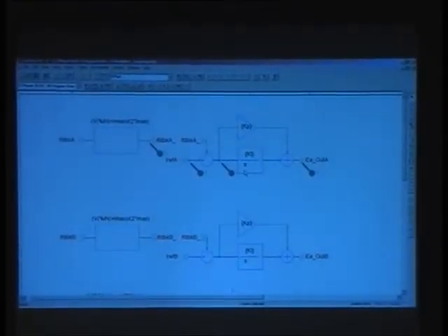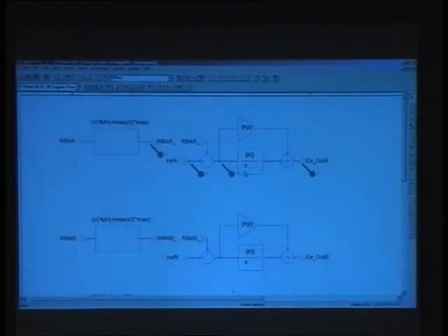You have I reference, you have I feedback, and then you have a simple PI loop. Here also we can run a Bode plot because this is a pretty linear system. So we can do a Bode plot and we can also do compensation. You are saying there is non-linearity of the torque, no? That's good. We can still do a Bode plot with non-linearity as long as there's no discontinuity.